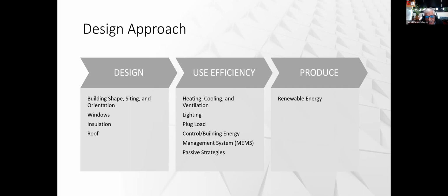How do you control building energy? The type of control that you put in there. And the reason is that, for example, for this building, the occupancy is from 7 a.m. or 8 a.m. all the way to 10 p.m. So the control system starts around 6:30, 7 o'clock, and then it shuts down at 11 o'clock. So we don't have any heating or cooling or anything between 11 p.m. and 7 a.m. This way you can save a lot of energy. So there is a special control system.